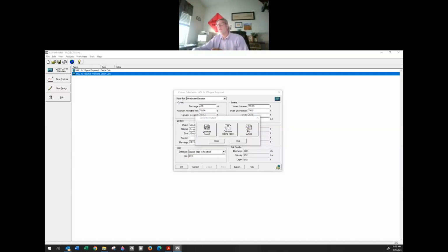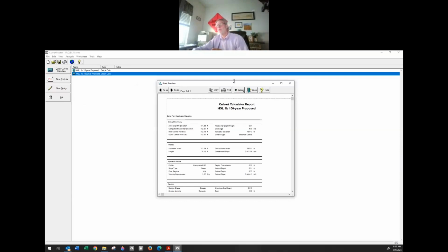Keeps coming up now. Oh, there we go. So we generate this report, and then you want to PDF this report and go ahead and save it now. And then in the end, somebody won't be stuck having to come back and PDF all of these at one time. And then move on to the next culvert or the next storm event that you need to look at. You want to do this design for the existing and proposed for the 10 and 100 year.